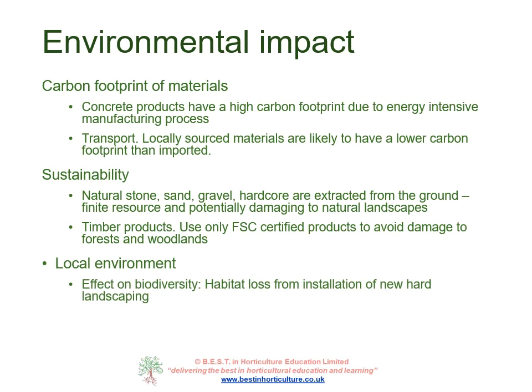Consider the local environment. Consider the effect of your feature on biodiversity, habitat loss from installation of new hard landscaping or new landscape features. Consider the water runoff from new areas of paving. What will this do to surrounding areas? What will it do to environmental flooding? So when we're planning new landscape features, particularly paved areas, we want to make sure that our areas are SUDS compliant.